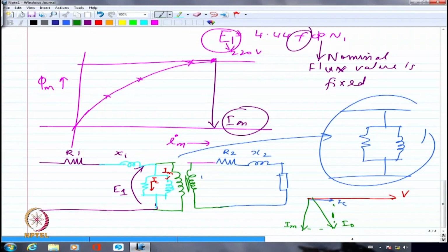That is what is my no load current. So the no load current of a transformer consists of two portions. One will correspond to the core loss component of current, which is fictitious. And the other one is the magnetizing current drawn by the transformer, which I would not say is completely fictitious, because you need that MMF